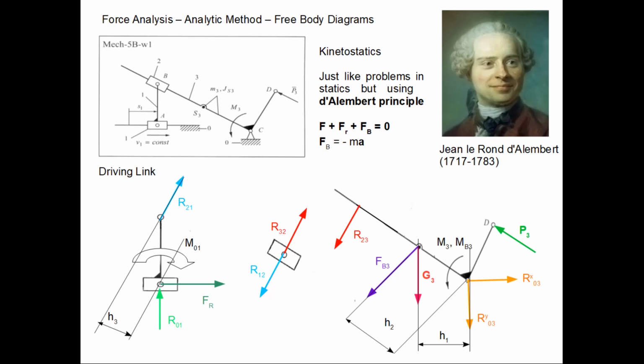So the sum of the forces along the x, y, z axes is equal to 0, and also the sum of the torques is equal to 0. But in case of our mechanism, these mechanisms are not in static equilibrium. They are mechanisms, not structures. So this static equilibrium equation does not apply to them. What applies to them is the Newton equation of motion. You know that the sum of the forces is equal to m times a. This is Newton's second law of motion. And similarly for the torques, you have the Newton equation that the sum of the torques is equal to I times epsilon. So these are not sums of forces equal to 0. Therefore this method cannot be applied to the mechanism.